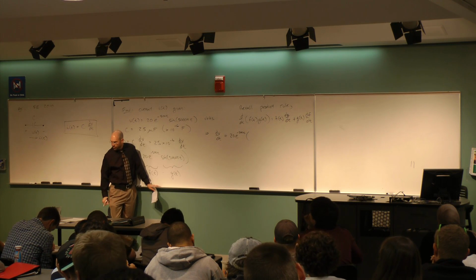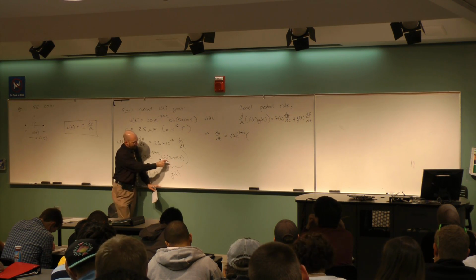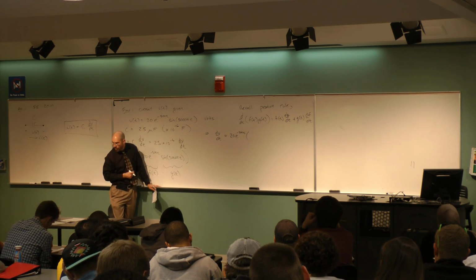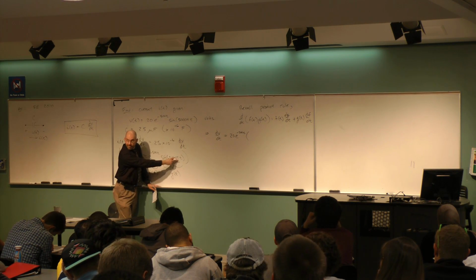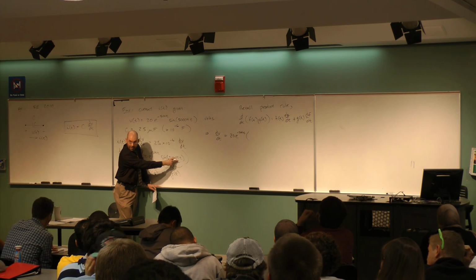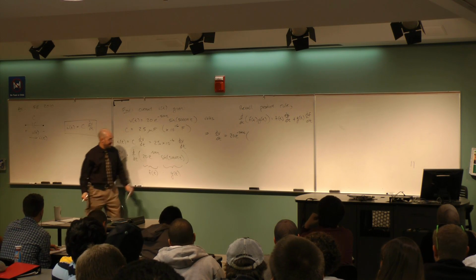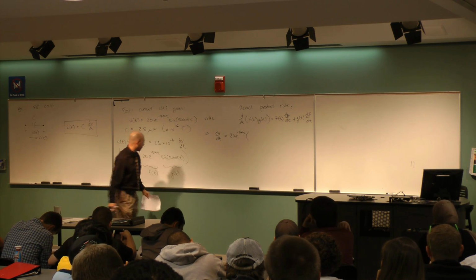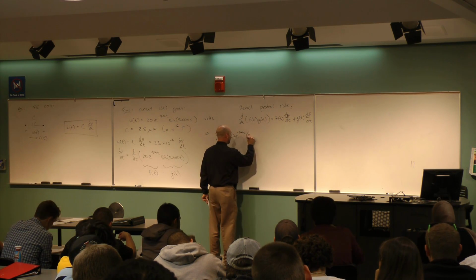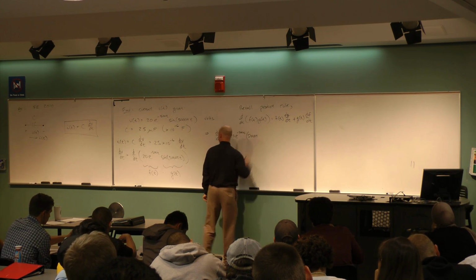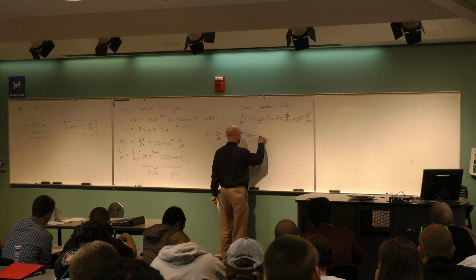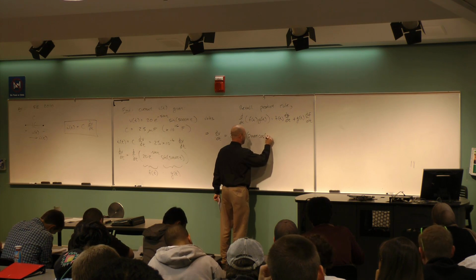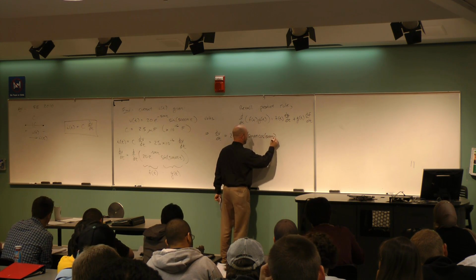So the sine function gives me a cosine, right? This is a sine of omega t. So when I take that derivative, the omega is the 5,000 pi, right? So that comes out front. So first function, 20 e to the minus 500t times the derivative of the second. That's going to be the 5,000 pi, right, times derivative of the sine is the cosine 5,000 pi t.